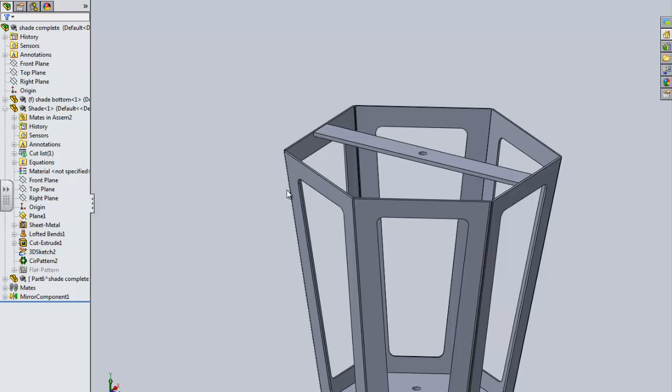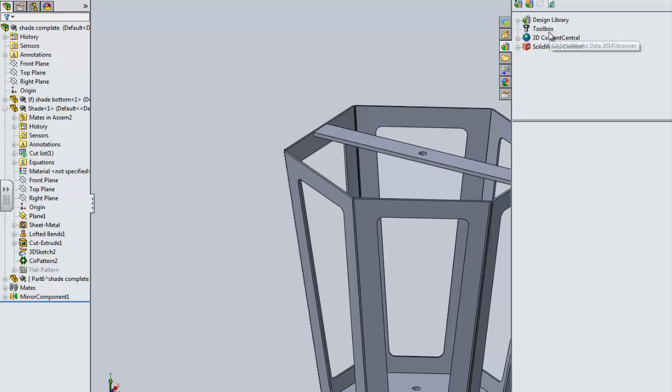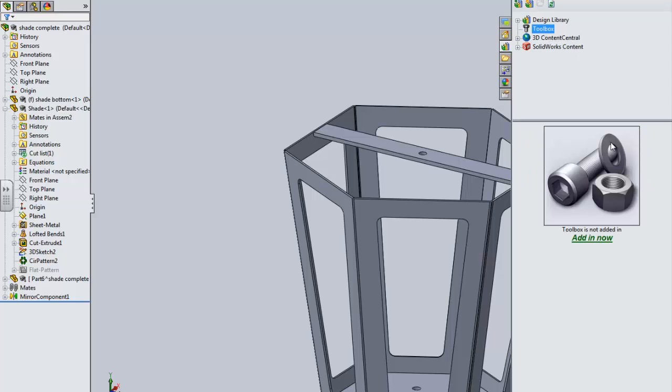And they finally want us to do the design library, which is interesting, and I hope it's set up. Otherwise, we're in trouble. Design library is right here on the right side. You click on that. There is a toolbox. So you click on the toolbox where you can pick all the hardware that are standard in both isometric.